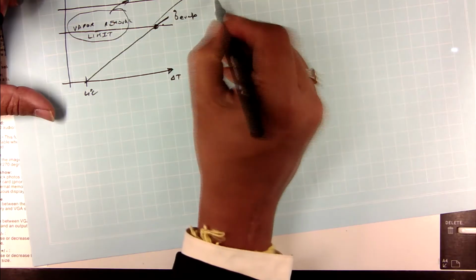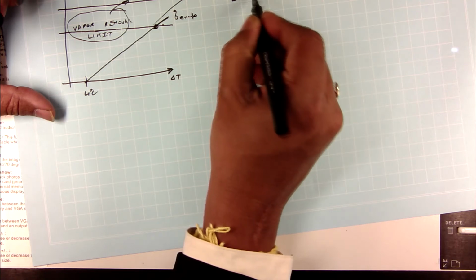And that's the fundamental resistance that will always be there, whether you have flow boiling or pool boiling, right? And that limit is probably much higher than your vapor removal limit. Okay. So that fundamental thermodynamic limit is the vapor production limit, isn't it? And I need to figure this one out.